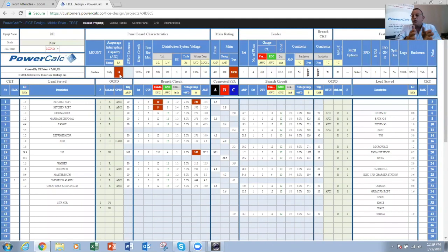So what's the relationship now between this and the short circuit current rating, the SCCR? The SCCR also has to be listed on that particular panel to be able to support that device's AIC rating. Now, if the entire system was rated for 10,000 based on the original calculation, and you decided to change this particular panel to a 14, really that panel is not going to be protected, because the entire system, or the panel itself, was 10,000, and you decided to change the main circuit breaker, or the branch circuit breakers, to the 14. So you really did not gain anything unless you change the entire system. So hopefully that clarified the differences between the AIC and the short circuit rating of the equipment.